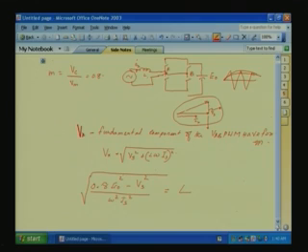Now, if you see here, this L value depends on Vs, which we know, and E0, which we know. Omega we know, omega is equal to 2 pi into F, our mains frequency. So, how to find out this Is? Is varies with our load, the load which is connected here at the DC voltage.